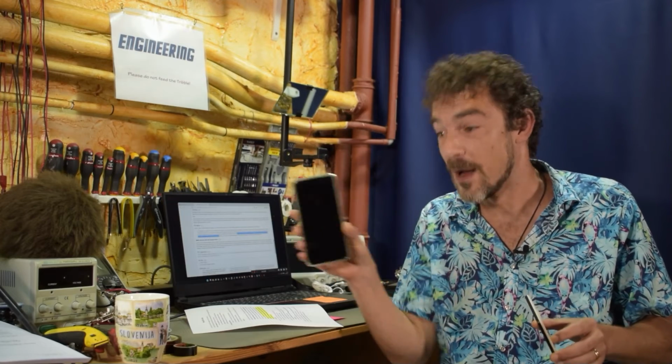The problem with that is that, yes, for that specific instance of WCDMA, this phone blasts my head more, but I'm going to be using GSM with this phone that has the lower SAR rating, so I buy this phone and I use it. But what I don't know is that this phone in the GSM tests is actually blasting the crap out of my head, but it has a lower SAR rating. For the specific GSM, at the specific frequency bands, in the specific position, this phone with a lower SAR rating in GSM could be blasting me more than this phone that has the super high SAR rating, making it evil.